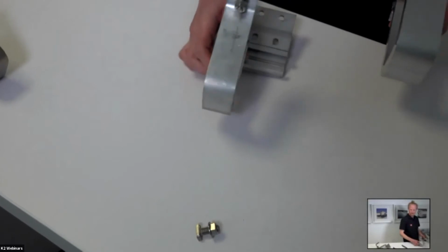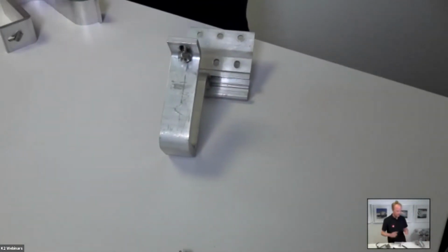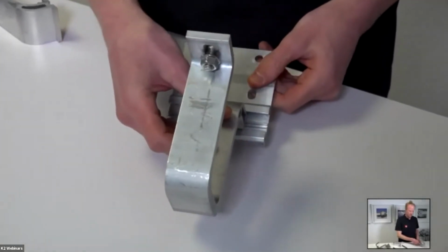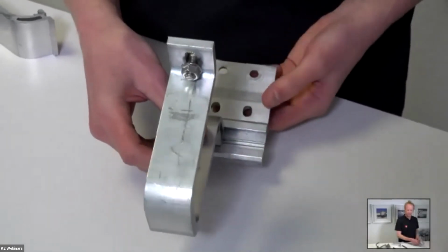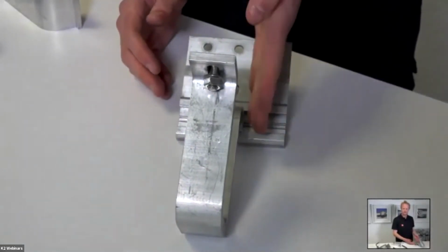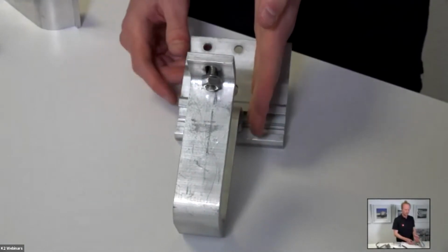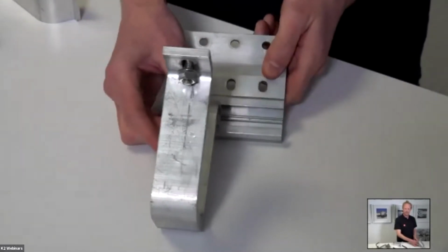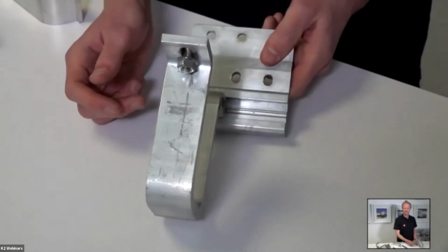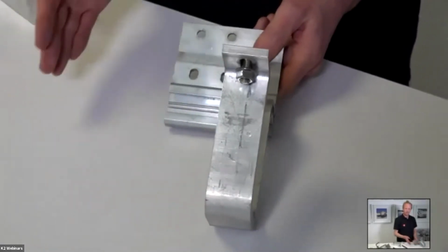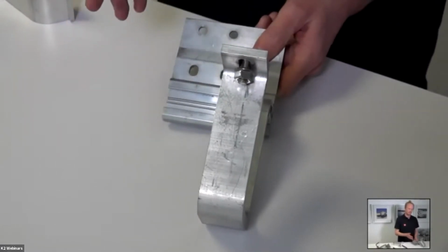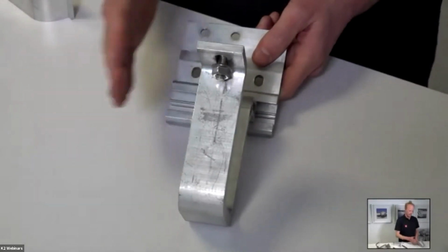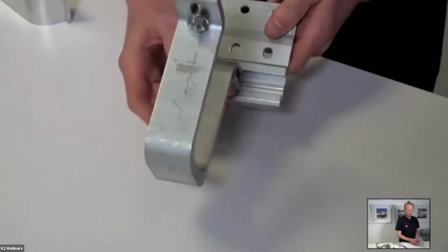And then I showed you this one earlier, but the SingleHook has a few different features. Instead of having a fixed base plate, there is a little bit of movement available here. So if perhaps the batten sits where my hand is here, the base plate could be attached to the batten, and then the roof hook could sit a little bit to the right, or a little bit to the left. You might want to vary this for the different tiles that are there. Perhaps the tiles don't match evenly with the battens, and you need a little more wiggle room, which can be very useful.